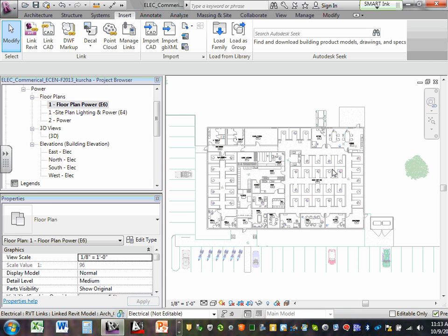Next project, when we have a two-story building, you'll say, Chad, I swear I brought my lighting in on the second level and it's not showing. Guess why? Because your lighting is sitting down here at 0 when you bring it in. So what you need to do, very easy, just shift it, put it at 10 feet or whatever the height of the ceiling is. It will shift it all the way up and slam it right into the ceiling. We'll cross this bridge when we reach it. You'll find it's not hard.